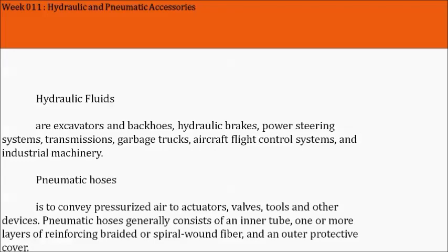Okay, another application: pneumatic hoses. What is the application of pneumatic hoses? It is to convey pressurized air to actuators, valves, tools, and other devices. Pneumatic hoses generally consist of an inner tube, one or more layers of reinforcing braided or spiral wound fiber, and an outer protective cover.